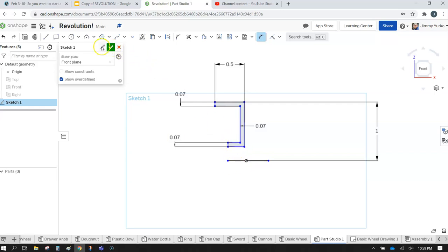And now it's time to establish the hole through the center. I'm going to build this so that it can fit on a 1/4 inch diameter axle. So remember that when we're doing a revolution, our measurements are half what the final product will be. Since the diameter is 0.25 inches, we're actually going to divide that in half, which will be 125 thousandths.